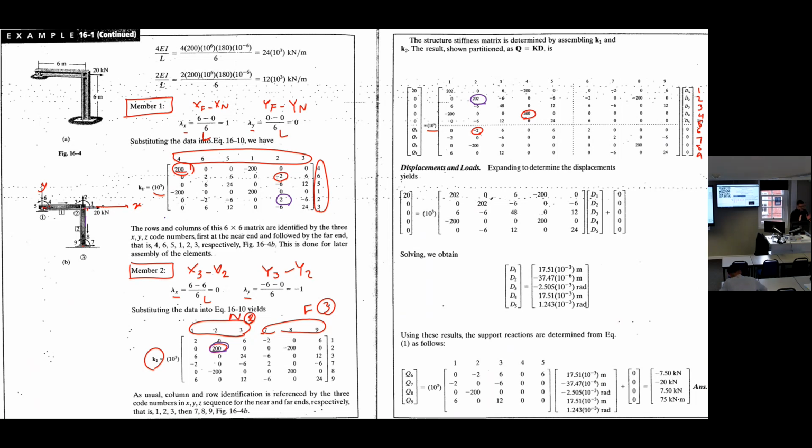Yes, you assume both ends to be fixed. You will have some fixed end moments at both ends, okay? Whatever you have at B, you put a fixed end moment at B as external forces. And what you get for the A node, you will take for the last stage and add with whatever support reaction you get for point A. What's the reason for doing that?